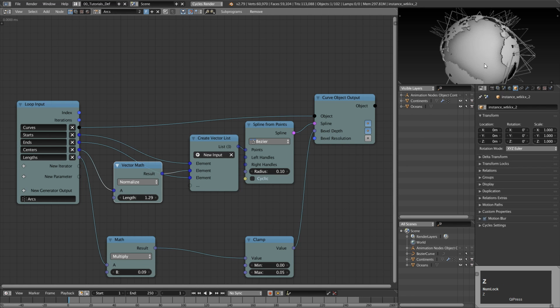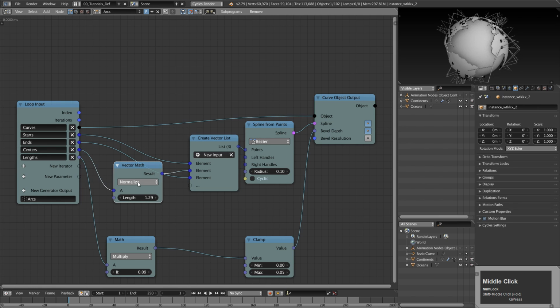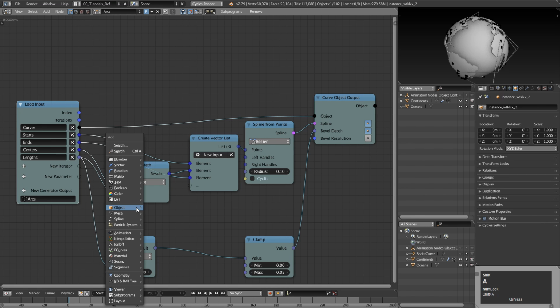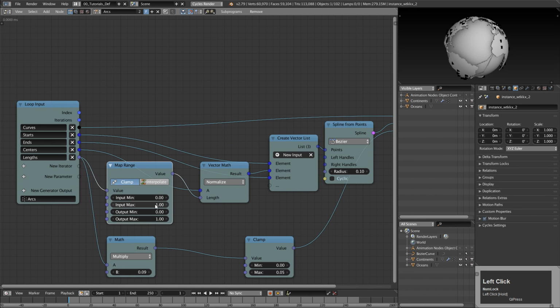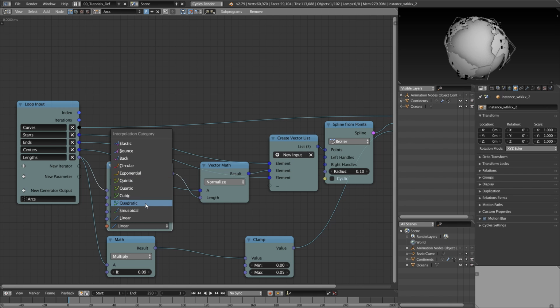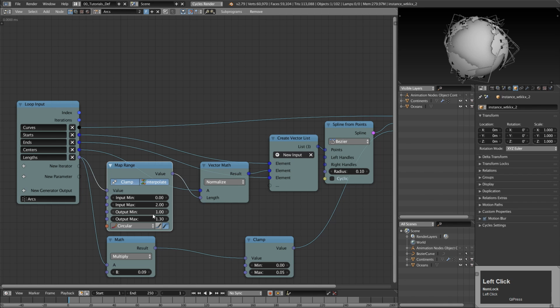It would be nice to control the height again with the length of the arcs, but putting it there directly definitely doesn't work. We need to remap the range of those values. The radius of the arcs is exactly 1, so the distance can be from 0 to 2. And we want our height to be from 1, which is directly on the surface, to something a little higher. I will go to 1.3. You can even try to play with the interpolation option.